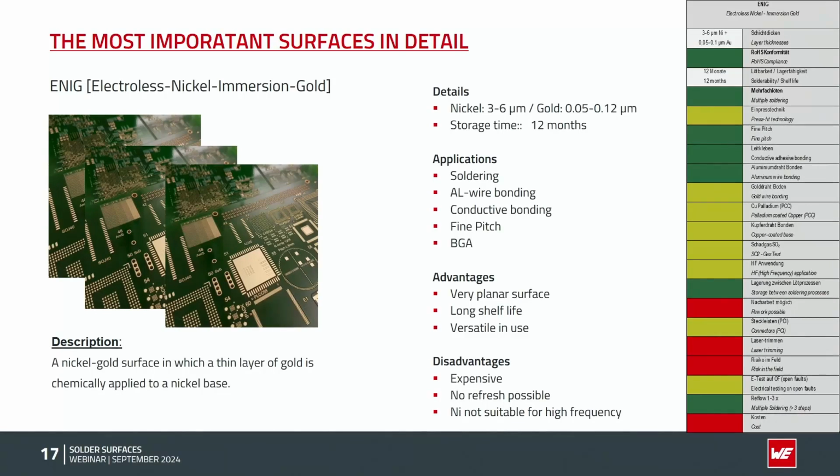And again, you can see on the right side the same structure of the rating regarding the different categories. It is RoHS compliant. You can do multiple soldering without problems. You can also use that surface pretty well if you have to dry PCBs prior to soldering, maybe rigid, rigid-flex or flexible PCBs which have to be dried.